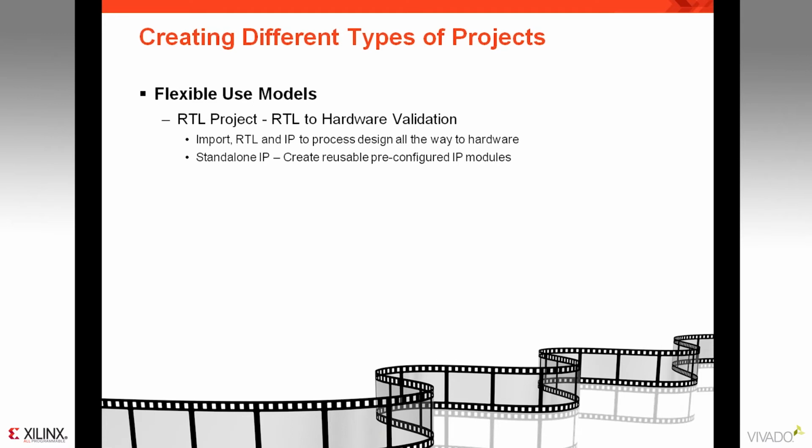You can also use that same project to create a standalone IP module. You can use the IP catalog to configure and implement an IP, and you can run it through synthesis, implementation, and logic simulation, all to validate it. You can also open up an empty project just to perform device exploration and examine device resources for the various types of architectures and devices.